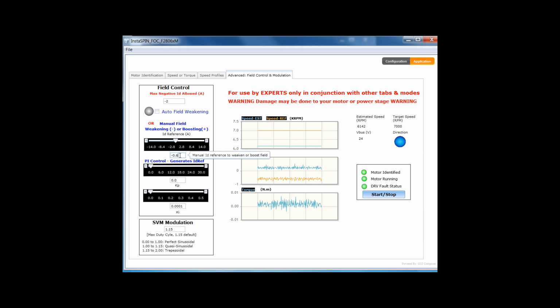So if we want to keep trying this a little, we can go ahead and get up to 7. Go ahead and put some more on here, and it's probably going to take more than an amp, so let's go ahead and move up. Getting closer. And there I am. I made it over 7,000. I think we'll come back down. Our speed loop will drive it back down right at about 7,000 like we want it to be.